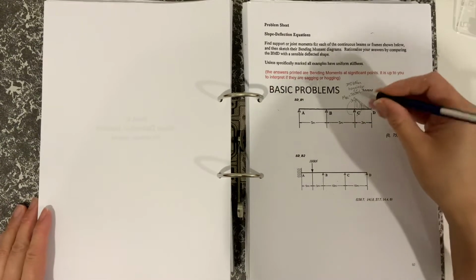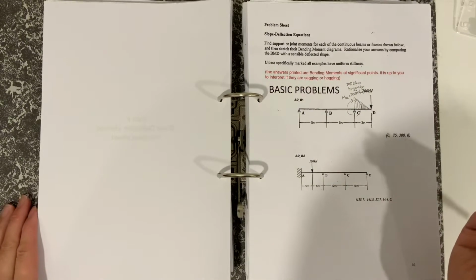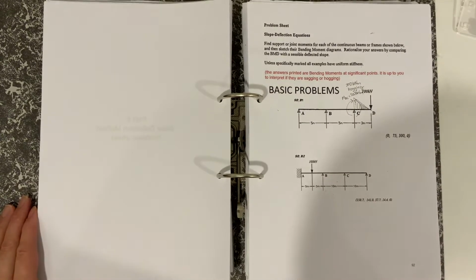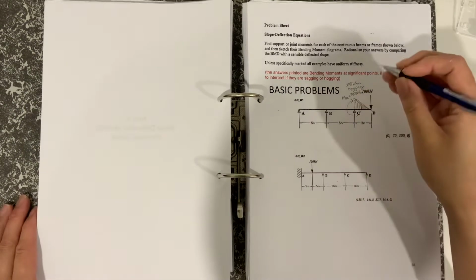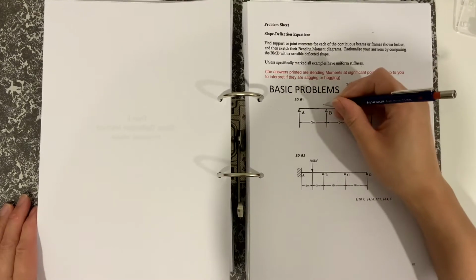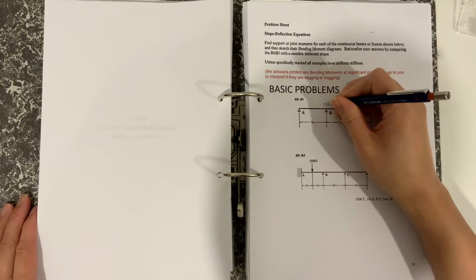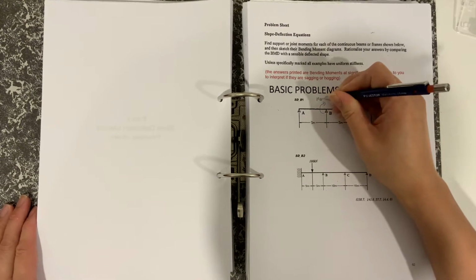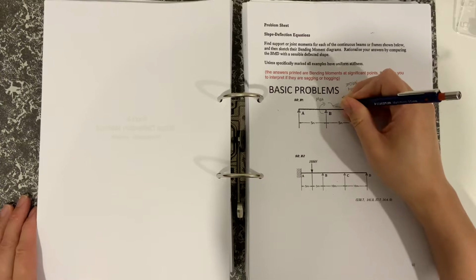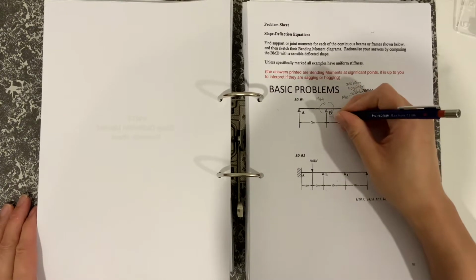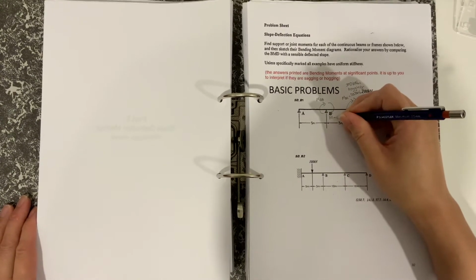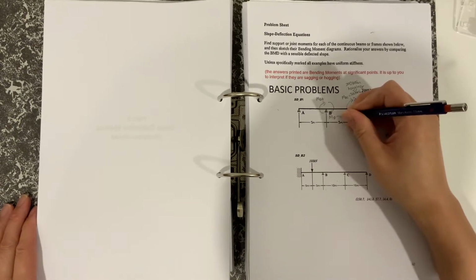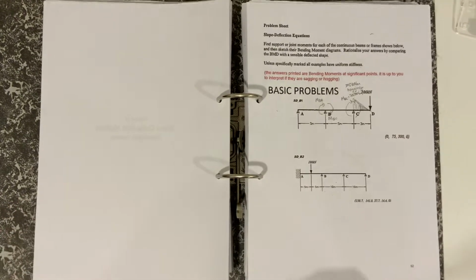And then on the other side here, when you do the slope deflection, we'll be trying to work out whether it's positive or negative, positive being clockwise and negative being anti-clockwise. So we would draw all the arrows on this side in the clockwise direction. We would put that as MBA, in that direction there, and we'll call that one MBC, which is also acting in the clockwise direction.